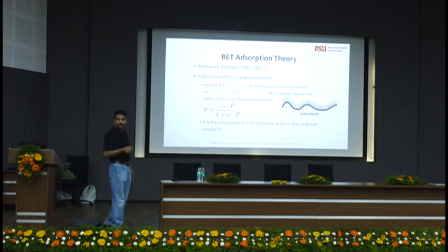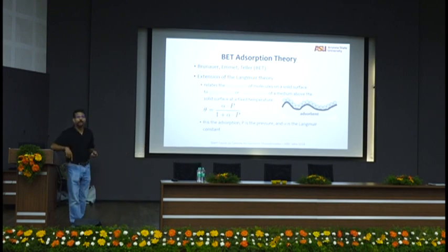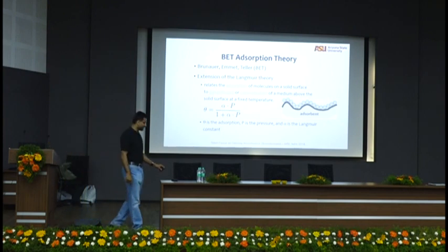So, BET adsorption, Brunauer, Emmett, and Teller, is a very common microstructural characterization technique. It's an extension of the Langmuir theory, where the adsorption of molecules is related to gas pressure or the concentration of a medium above the solid surface at a fixed temperature.